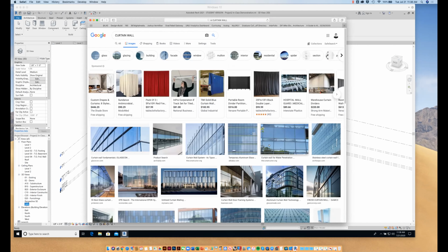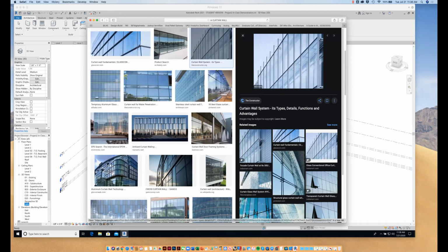Most exterior wall systems in buildings these days are just hung like a piece of clothing on the slabs and the structure of the building. Even masonry, like bricks and block, usually aren't structural anymore. Those are hung just off the side and stacked accordingly. So what we mean by curtain walls is that you have mullions and glass panes, and usually 2 or even 3 sets of glazing in between with an airspace and argon pumped in there to give it more thermal performance. Basically this is holding itself up and then clipped onto the structure behind.